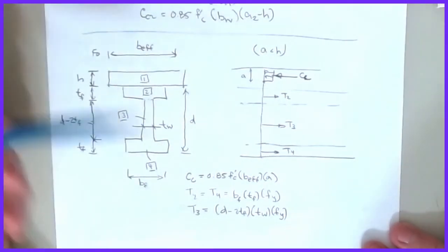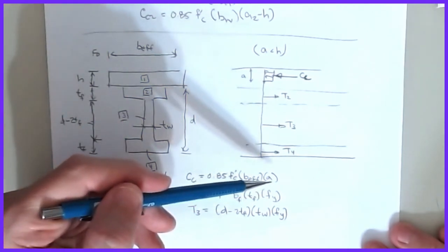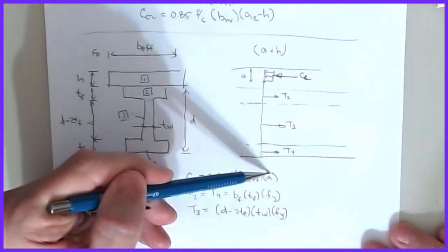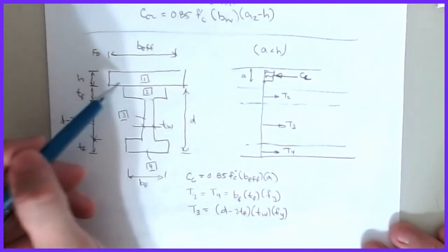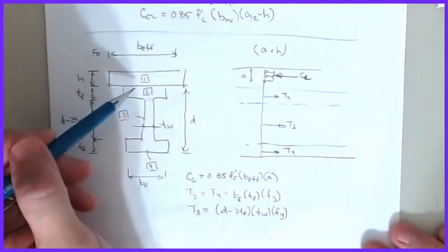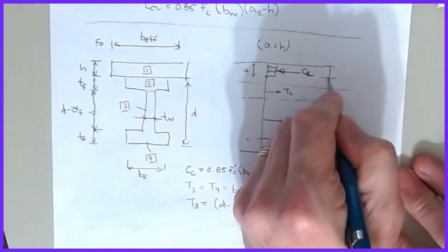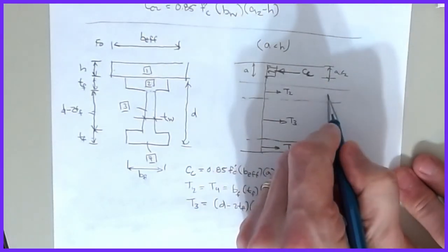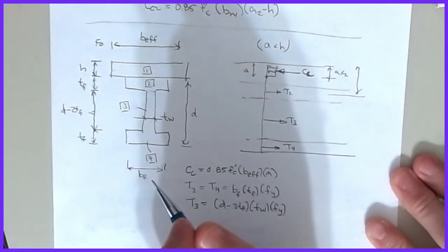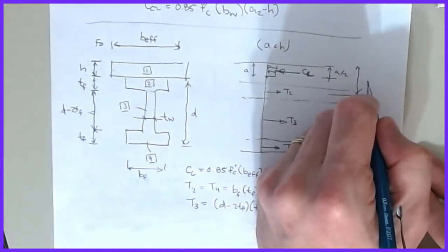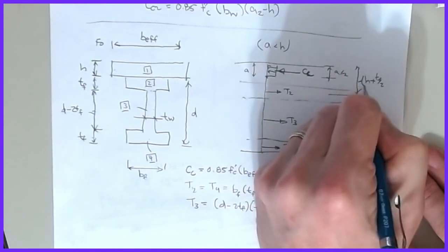So it's the same basic approach that we set up. And so the only unknown in all of this is going to be this little A guy. Okay, for the case where A is still up in the slab on this case. Now again, you have to know all the distances on this thing, right? This is A over 2. This distance is going to look like, what is it? TF over 2 plus H. Yeah, H plus TF over 2 gets me this guy.